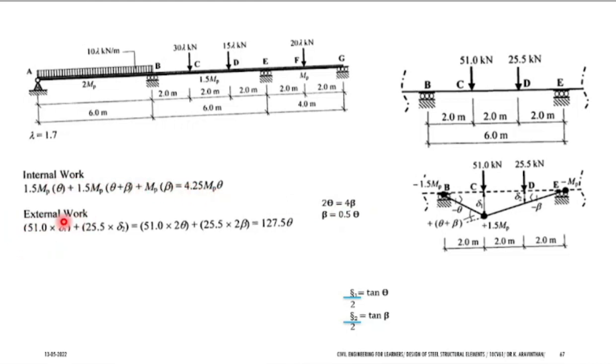Then for external work done, it depends on the applied load. Note the difference between internal and external work done. Internal work done depends on moment. External work depends on force. In all the previous problems, you find the difference. Always internal work will depend on moment.